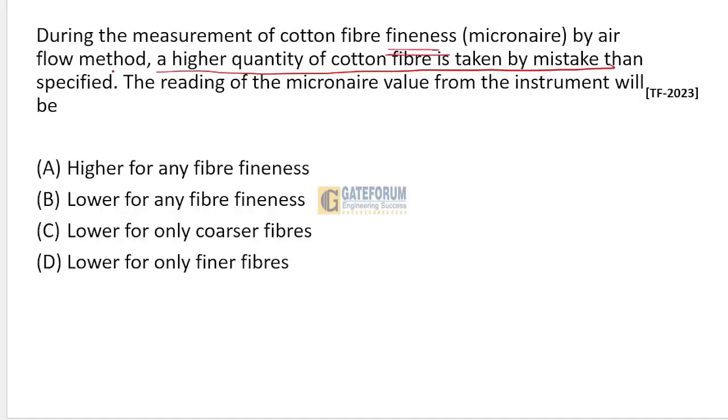It would be higher for any fiber fineness, lower for any fiber fineness, lower for only coarser fibers, or lower for only finer fibers. So basically you need to know that if a higher quantity is taken, then the micronaire value would be lower for any fiber fineness. That means it does not depend upon the fiber fineness. Basically, if a higher quantity of fiber is taken, the airflow resistance will be higher, leading to a lower micronaire reading.